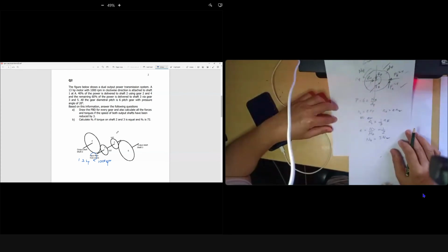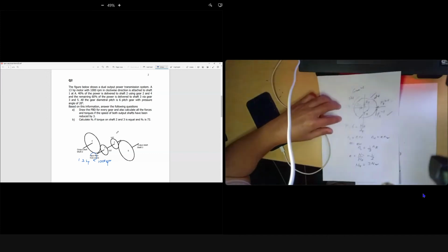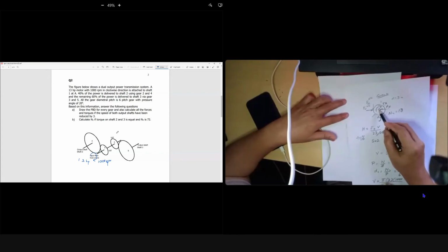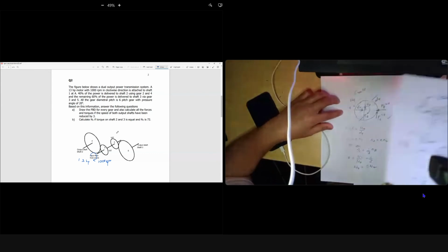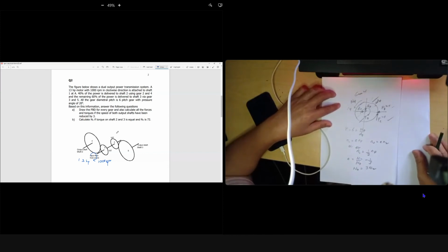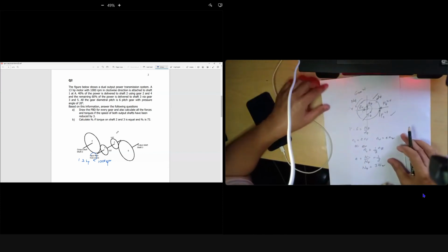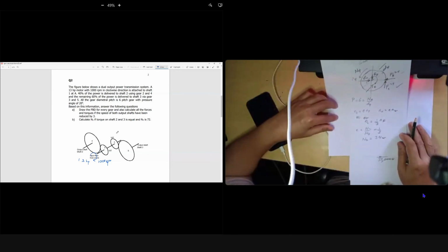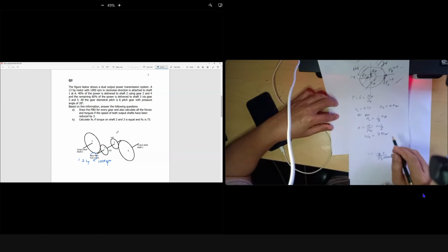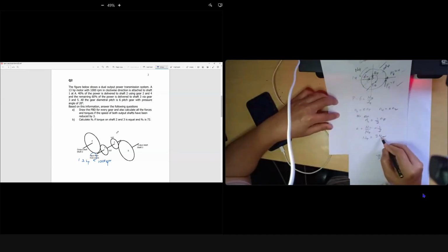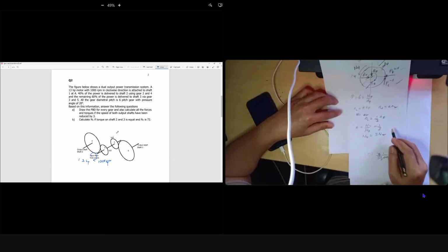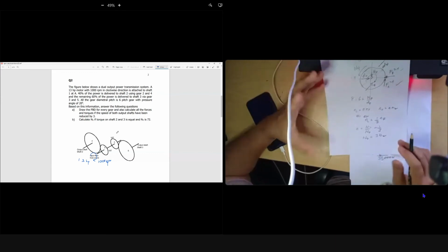Since the power is changed from 40 to 60%, something like that, but the RPM is still the same, right? The revolutions per minute, the 1000 one, there's no change. The input speed from gear 2 and gear 3 on the same shaft is still 1000 RPM. But the shaft of your gear 4 is reduced by 3. So what is the reduction of speed? It's simple: if reduced by 3, the bigger the gear, the slower the speed.